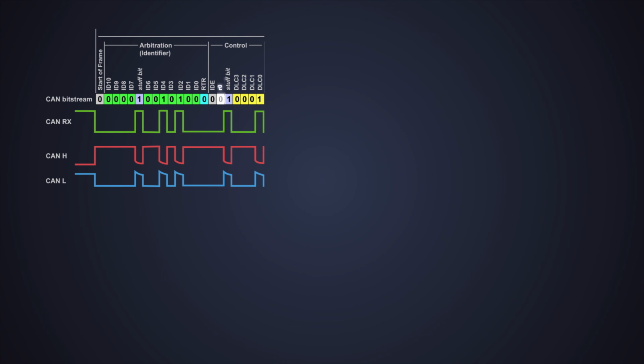The R0 bit is reserved for future purposes. We see this future purpose bit many times, but what it means is that there may be some features that can be added in future which can use this bit, maintaining compatibility with the older devices. And after that, the data length code is a 4-bit code which specifies the amount of data submitted in terms of bytes. A message can be 8-bit, 16-bit, 32-bit or 64-bit wide. Based on the message byte length, this DLC changes.